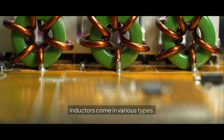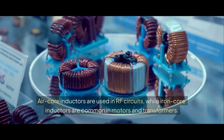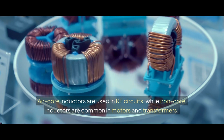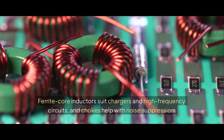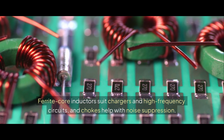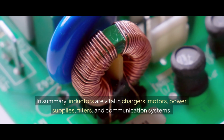Inductors come in various types. Air core inductors are used in RF circuits, while iron core inductors are common in motors and transformers. Ferrite core inductors suit chargers and high-frequency circuits, and chokes help with noise suppression. Symbols of these inductors are as shown in the summary.